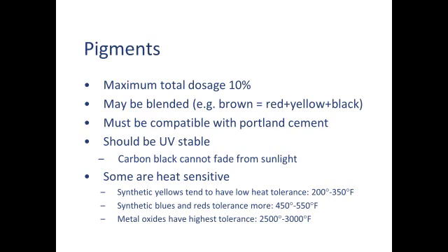So I made some samples with it, got all excited, and I made a small little side table just to kind of put in my showroom at the time. And I cast it. It was this brilliant ultramarine blue, gorgeous. I came into the shop the next day, pulled the forms off, and half the blue was gone. Some of it was gray, some of it was sort of a bluish gray, but none of it was the intense blue. And that's because the pigment was not stable in the alkaline environment of Portland cement-based concrete.